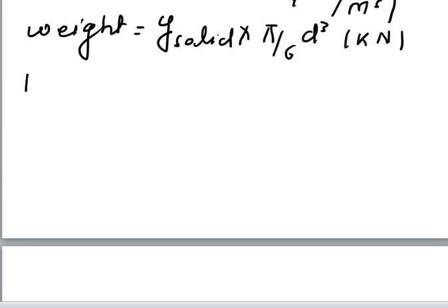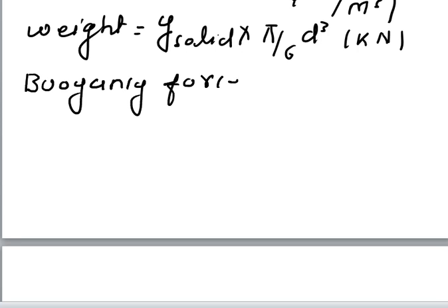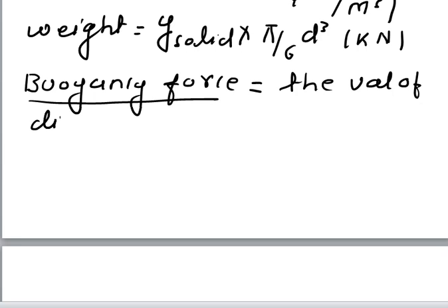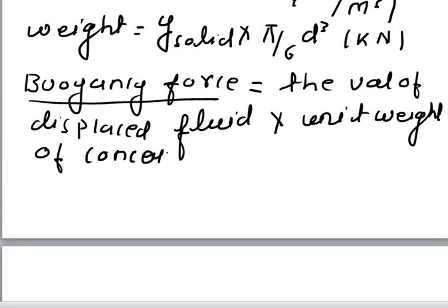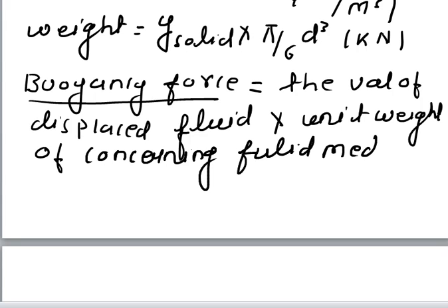So what is buoyancy force? Buoyancy force equals the volume of displaced liquid, displaced fluid, multiplied by the unit weight of the concerning fluid medium. In this case we assume a water medium.